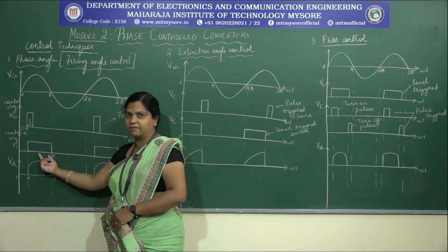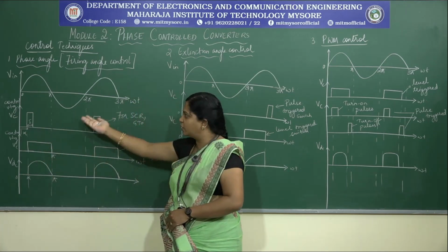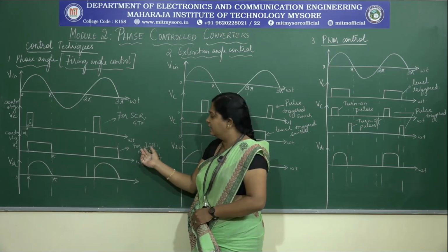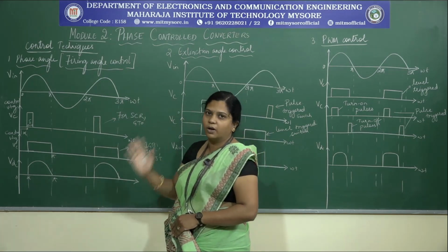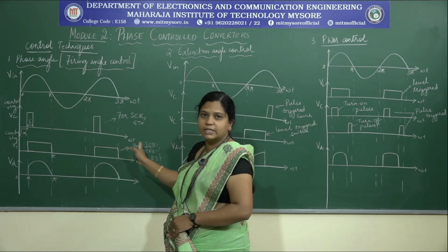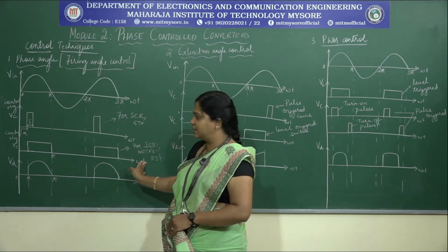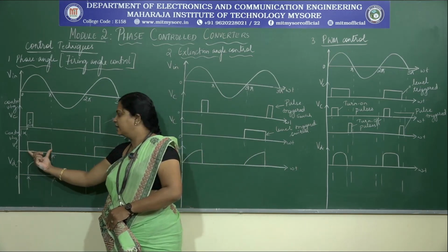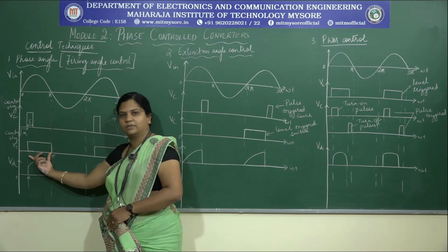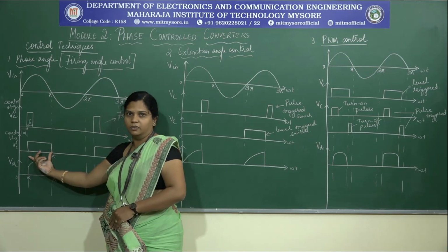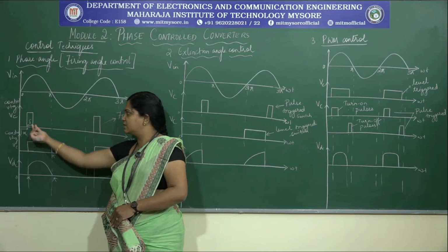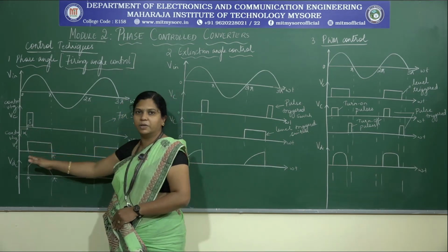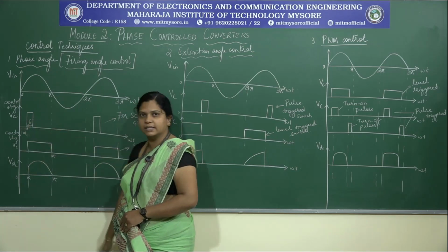Power is being saved. Whereas if you use a member of the transistor family such as an IGBT, MOSFET or BJT, then you have to provide the entire signal, meaning for the entire time you want it on, you give the complete signal. So this is a pulse and this is a complete signal that you are applying. Here loss of power will be more, so usually we prefer the thyristor.